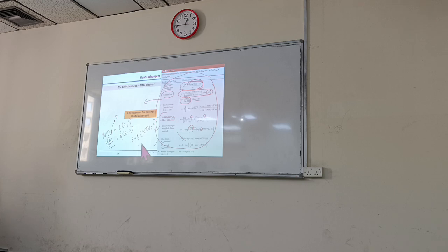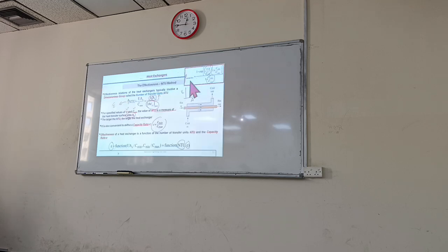You have something like this, but for h it would be very good. h is there inside U. For defining h, we have only experimental correlations. h is still so complex, especially in turbulent flow. For laminar, yes, you can develop simple mathematical forms.